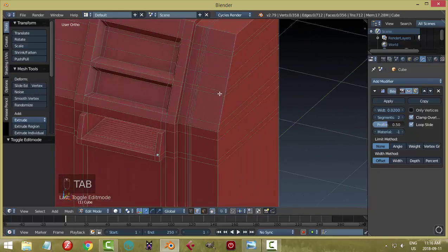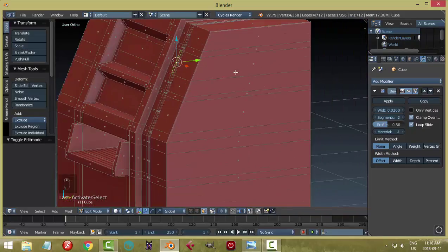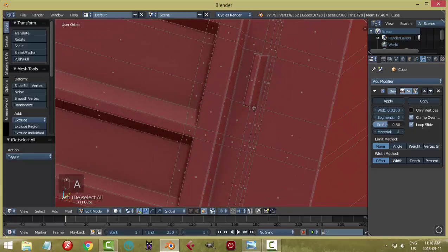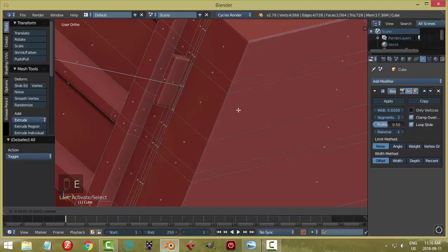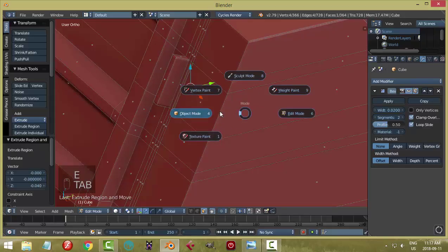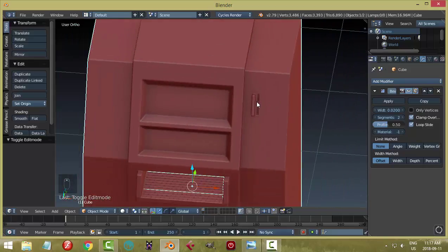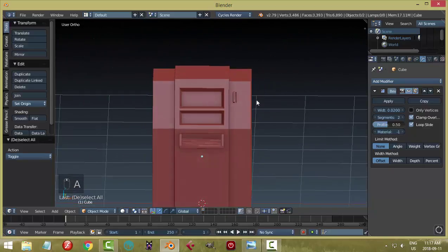Let's go back into edit mode, and what we're going to do is find those regions, go into face select. This one is going to come out, so let's now just hit E and pull out to maybe there. And this one, not the one right beside it, give a little bit of space. That one is going to be indented in. E, and I'm going to just pull in. It doesn't have to go in too far. There, just like that. So you'd put your debit card in there, and this is some other little piece. Cool. So far, so good, right?